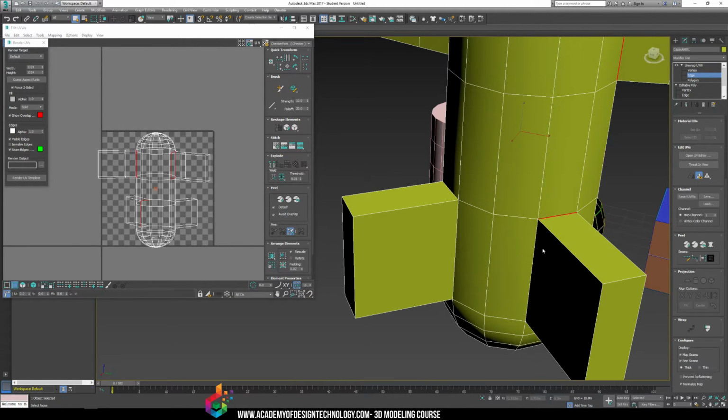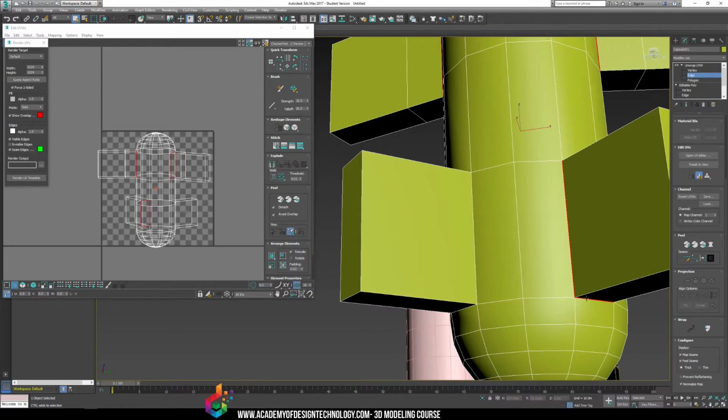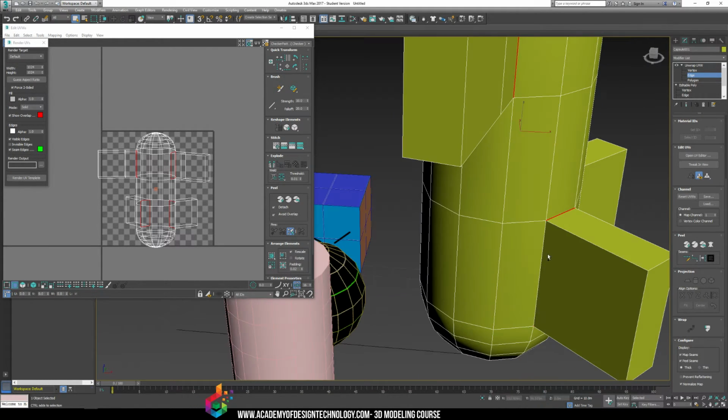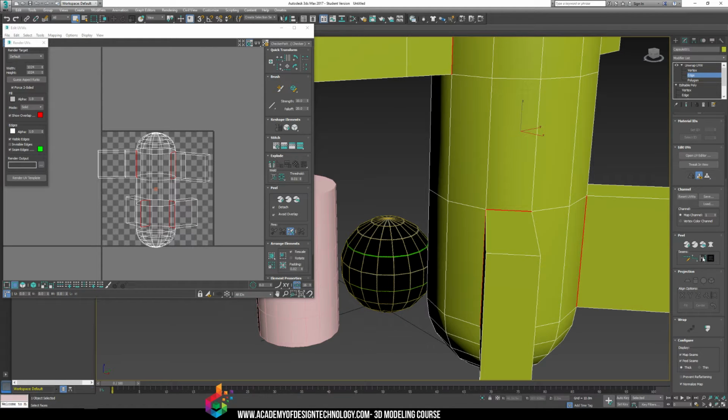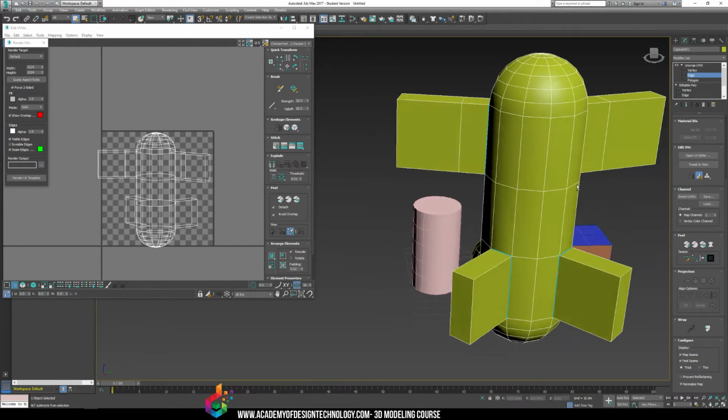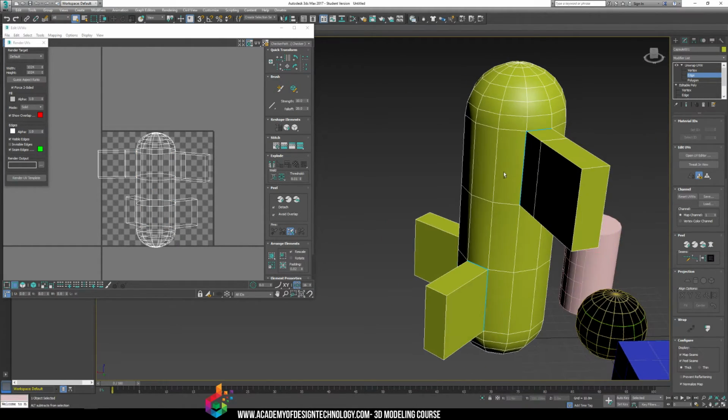And this part down here. And let's go around this part over here. And I'm going to go to this part of the menu where it says Peel and Seams, the sub-menu Seams, Convert Edge Selection to Seams. Now that I have clicked on it, you see that those edges turn blue. Those blue edges indicate that they are now seams.